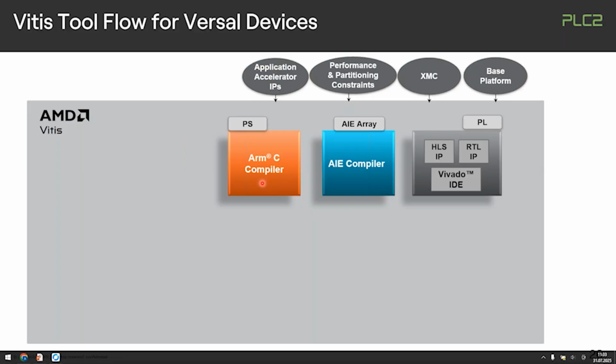You can create the ELFs for a single core bare metal, but you can also create them for Linux operating systems that abstract away the number of processors you have. So any kind of this is possible, but it's the GCC flow that's the important thing. In this case, you would not be able to use that flow to create the HDL side. And that's basically why you have a distinct project flow for these kinds of targets.